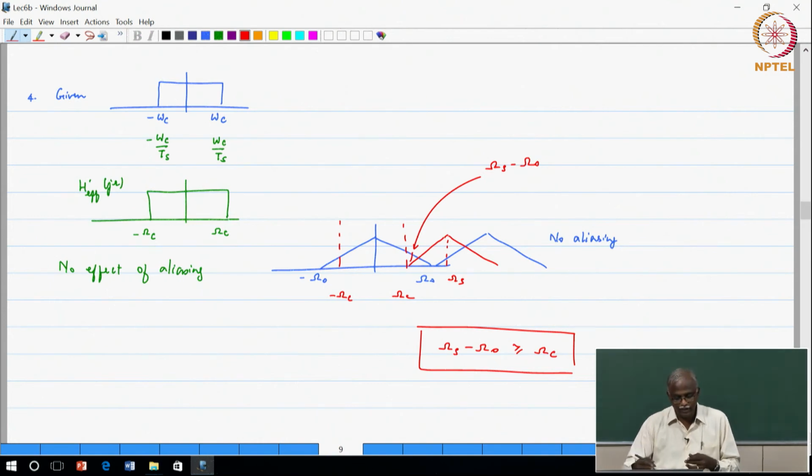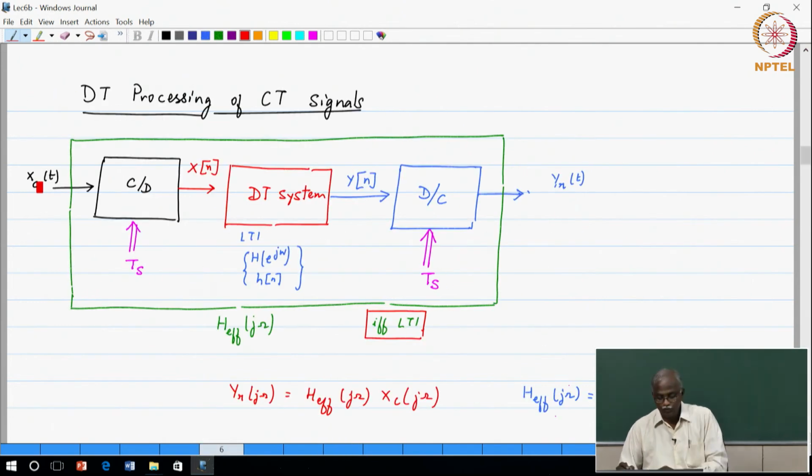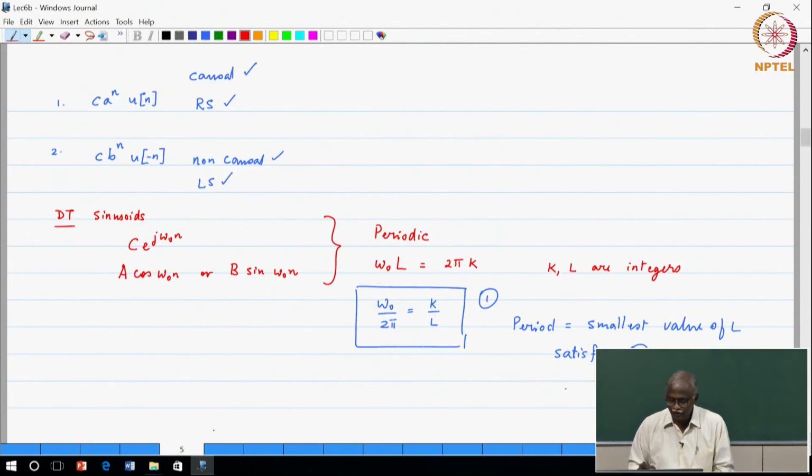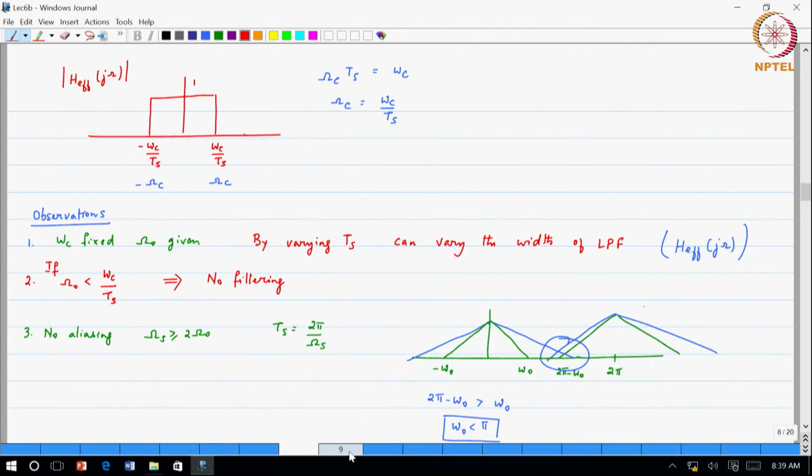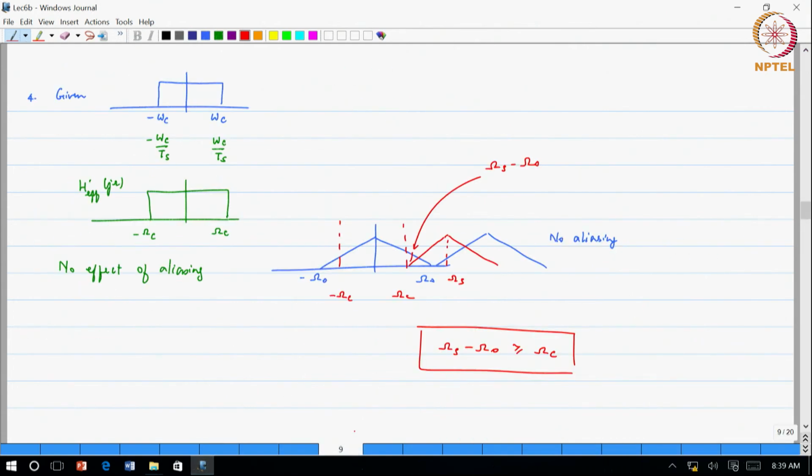So in this particular example, do I need an anti-aliasing filter? If you are not band limited to omega naught, then there is a problem, because what would happen if you are not band limited to omega naught? Can you please sketch for me what that would look like? Okay, if it was not band limited to omega naught, then my input spectrum would be something much wider, and I would pick omega s as before.